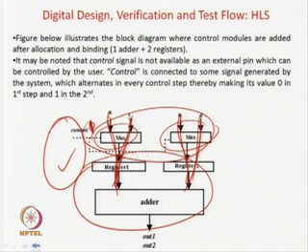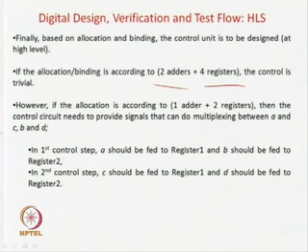So, high level synthesis not only goes for scheduling, allocation and binding, but also it will tell you how the controller will behave. Because if you are going for this small structure with 2 multiplexers, 2 registers and 1 adder, then you also require a controller. So, high level synthesis will also tell you how the controller will behave. That is what is being said.